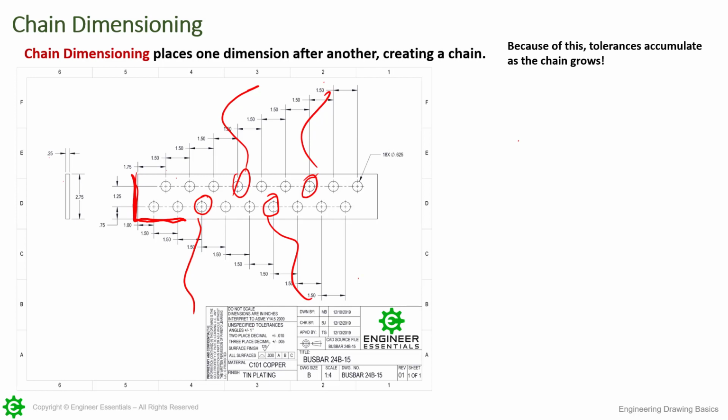I've seen instances where, especially for long parts that don't fit fully inside of the machining center, they will use baseline dimensioning for it, so that the machinist can just advance from hole to hole, understanding that there's going to be quite a bit of stack tolerance down the 20 or 30 foot length. But they don't care, as long as the relationship of just this one to this hole is good, and then from this hole to this hole, and so on and so forth. Maybe there's actually going to be a slotted tab that goes over this with two holes, but it's only going to be over those two holes. Well, then this relationship has nothing to do with this corner, so it wouldn't matter.